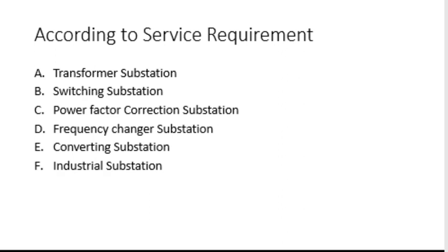Then the most important question that comes to my mind, and should come to yours also: why do we need HVDC lines? HVDC lines are needed because they operate at 0 Hz, the basic funda. When we have to connect parts of India operating at different frequencies, two areas with different frequencies cannot be connected or synchronized directly. So if we have a line operating at 0 Hz, a high voltage direct current line, then we can connect those two areas and synchronize them.